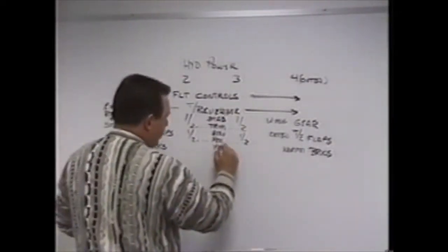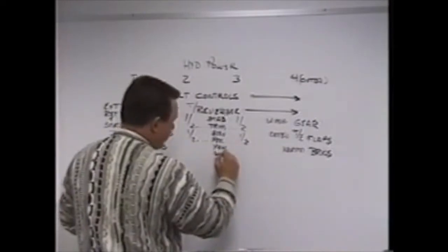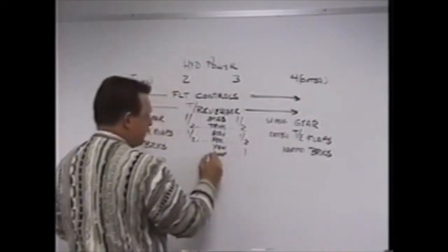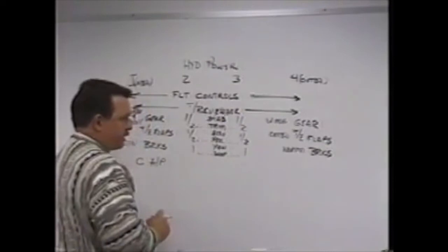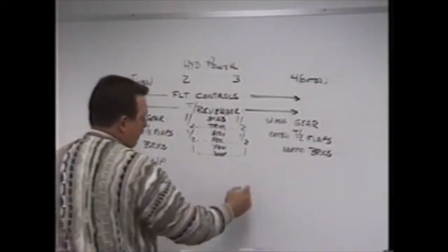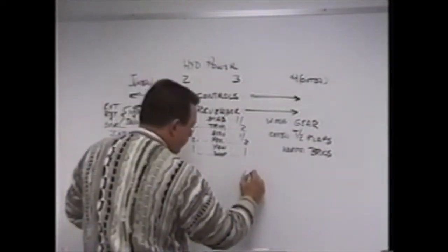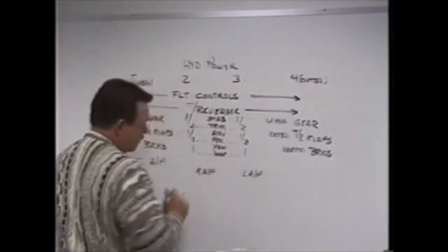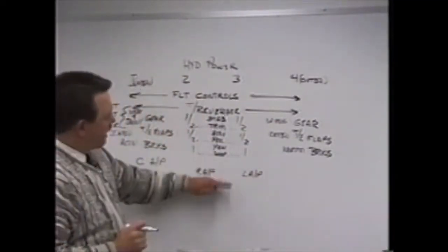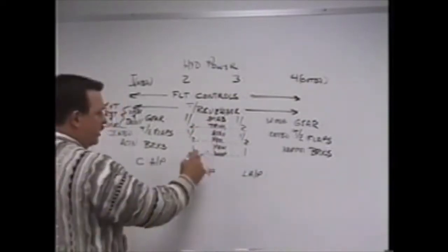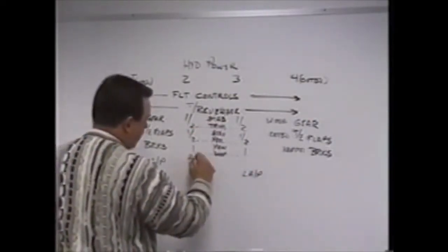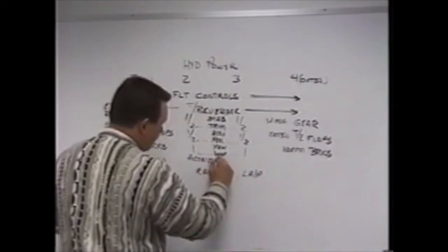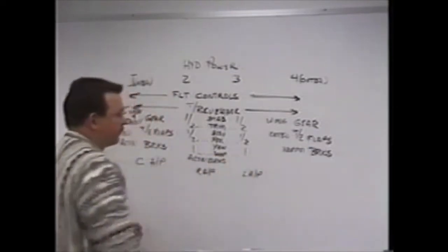Each rudder has a yaw damper. One of them is pressurized by System 2, the other one by System 3. Autopilot servos: the left autopilot servo is on System 3. The right autopilot servo is on System 2. These are items that are common. The only difference between 2 and 3 is that 2 has alternate brakes. There is no brake source on System 3.